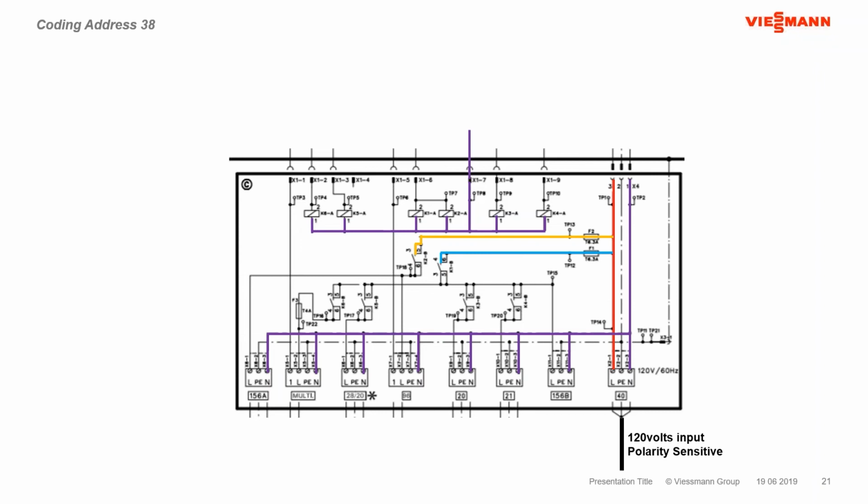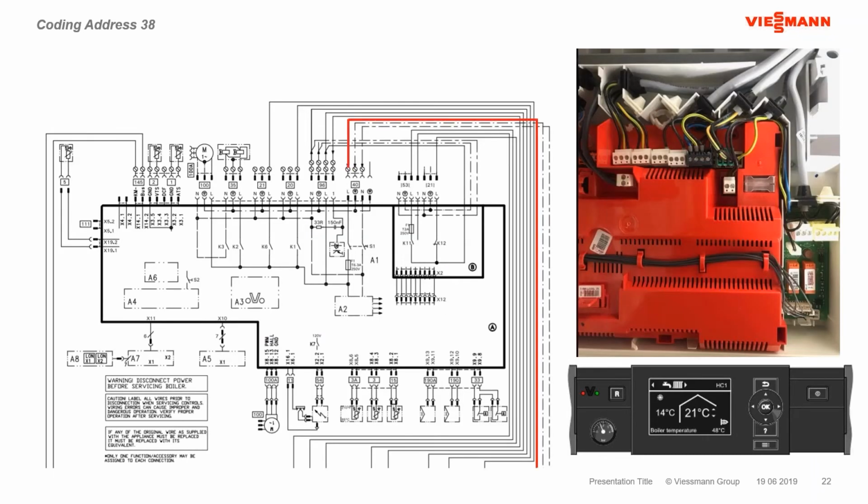That's what happens. The line voltage does the same thing. So it hits the 40 plug at the top of our control console, goes to the power switch. Now that the power's on, it moves past that to another fuse. So now this is the control console fuse that protects the control console.